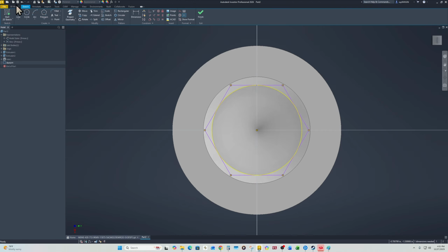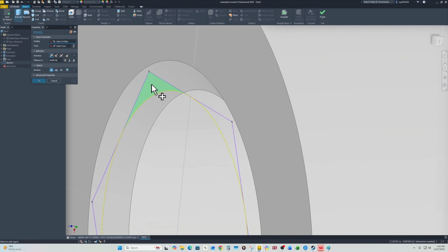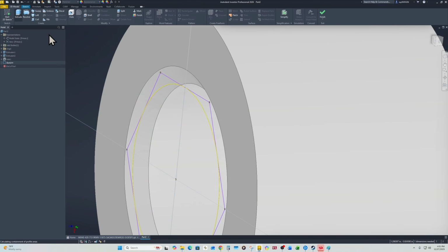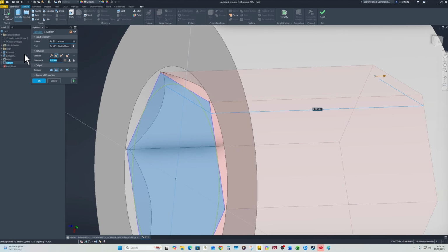Should be good. 3D model, extrude. And if it's doing this, where you have to do this, one thing you can do is just select the line until everything highlights. You can just shake it a little bit. You know what I'm saying? Shake it, and click on it. Select the other side. I believe it's 0.307. Select cut, and then 0.307.